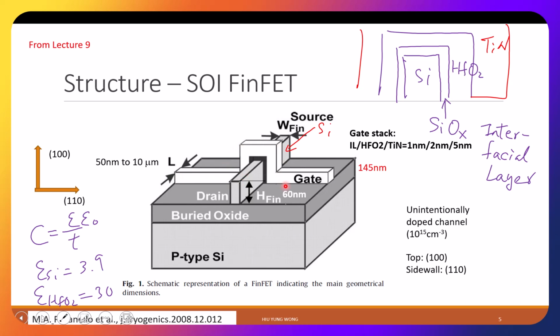We have the gate, right? And then we have fin. This is the drain. This is source. The current travels from drain to source controlled by the gate. And particularly, I emphasize that you should know that if we do a cross section, I'm cutting here on the screen, right? Then I will see this fin, right? This is the silicon. Current is traveling perpendicular into the screen.